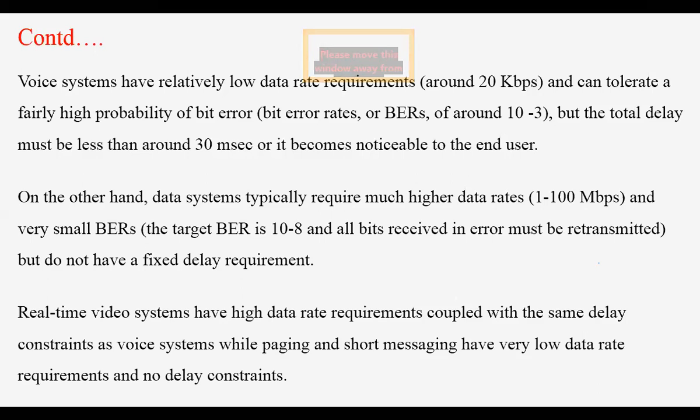So when we say it is voice communication, what we require is low bandwidth, which I can tolerate. I can tolerate probability of error up to a certain extent, say 10 raised to minus 3 and that range. But if the delay is noticeable, it is annoying. For voice communication, these requirements are different. So we have noticed that bandwidth, probability of error, and bit rate are the three important requirements from the user point of view.